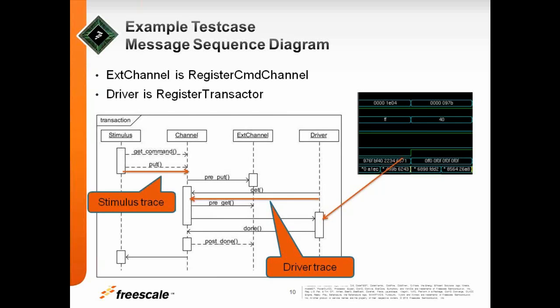The other side, of course, if you have your stimulus here and you see there's a read or write happening, but you don't know what driver is actually playing the music for this, and you look at the call stack, you will see it's also just ending somewhere in the infrastructure, but you don't get to the driver with that. And this is just an example that shows you how you can leverage transaction recording to make your debug easier. You can apply this to interrupt service routines, register accesses, mode changes, and so on. This is just one example.